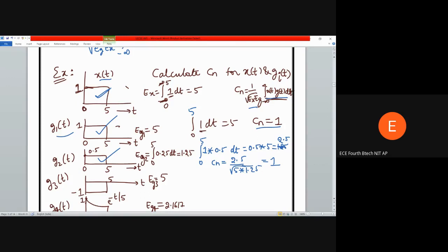When you define the correlation coefficient, one important point we define for vectors is that it should be independent of the magnitude. So if I apply the concept to signals, it should be independent of the amplitude of the signal, because amplitude is directly related to the energy. That means it is actually comparing the shape of the signals. That is an important thing that you should know.